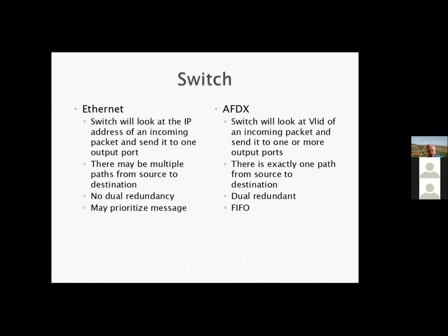But if I have 101 devices like that, I've got a problem, because then I've got 1.01 seconds worth of data that I would like to transmit every second. That's not going to work. So I don't design the plane that way. Now, let's say I've got all these boxes and I absolutely need that to happen. I won't use one AFDX network. I'll switch it into two AFDX networks. Not that that's necessarily a simple thing to do, because if there are two networks, then some of the boxes can't talk to other boxes. Work it out. Not every box on a plane has to talk to every box on the plane.